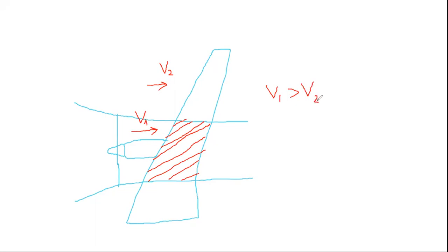And what we have from this, we have an increment in lift and an increment in drag, because the lift and drag forces have a speed term in their formula. For example, lift is the lift coefficient, I use the Russian system of notation but it's exactly the same for the English system, times S area times air density times squared speed divided by 2.